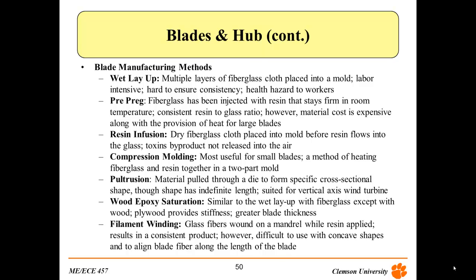Filament winding. Glass fibers wound on a mandrel while resin applied. Results in a consistent product. However, difficult to use with concave shapes and to align blade fiber along the length of the blade.